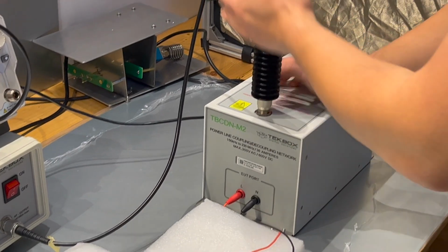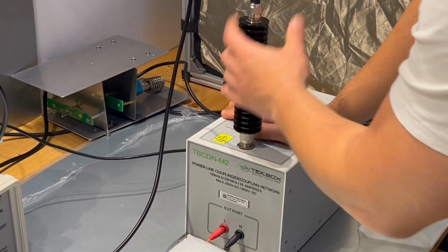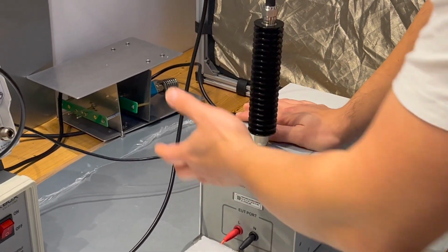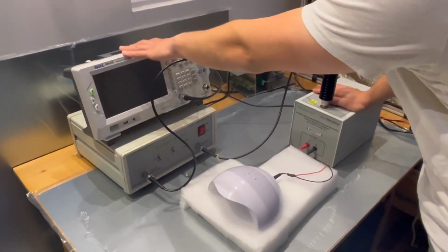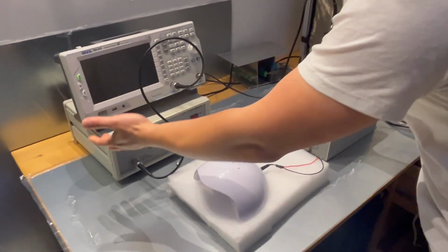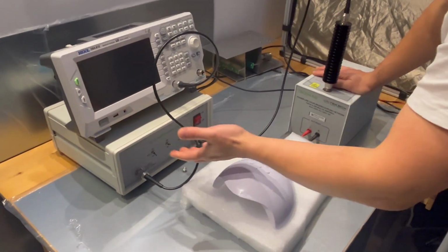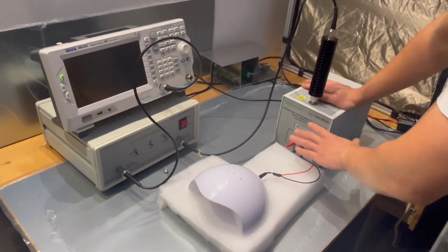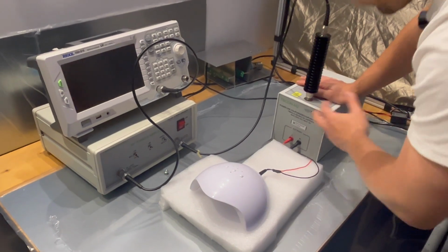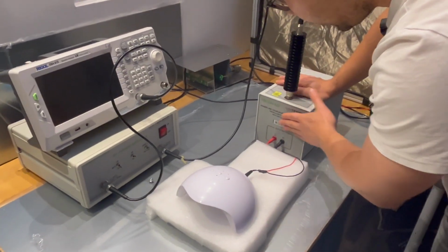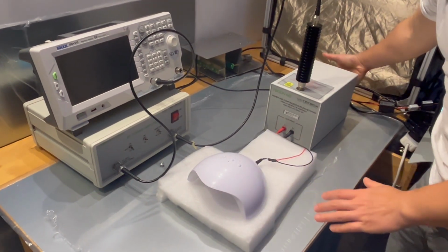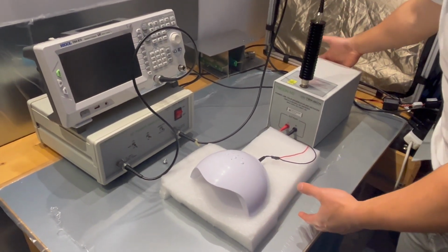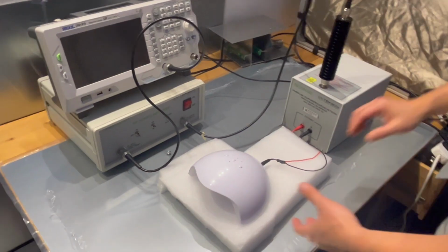And here, as you can see, the 6 dB attenuator we're still keeping. This part of the setup is exactly the same. The spectrum analyzer provides a signal source, the amplifier amplifies the noise, and then it gets injected into the CDN. This port is the EUT port, which will be connected to the device under test. The other port is the AE port, which in this case is connected to the power.